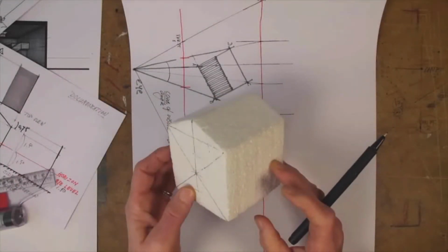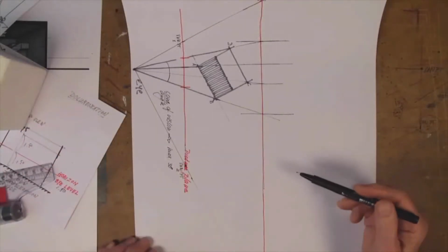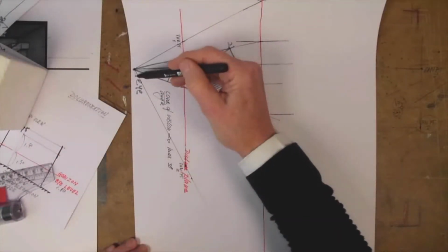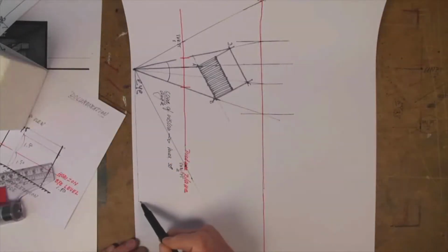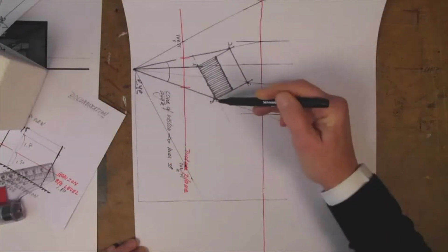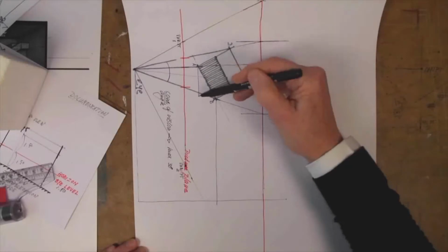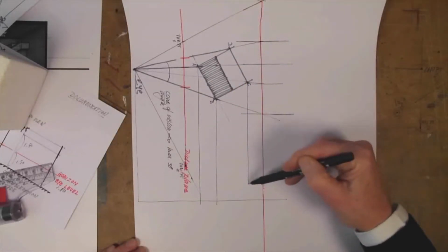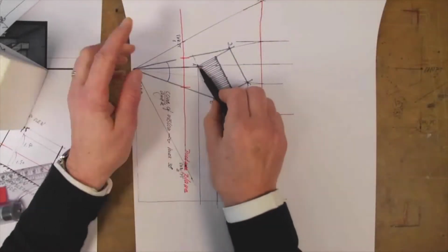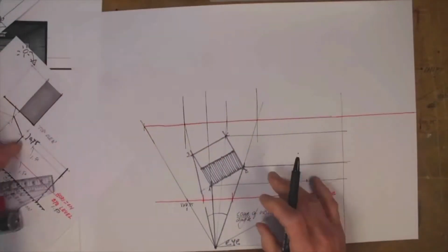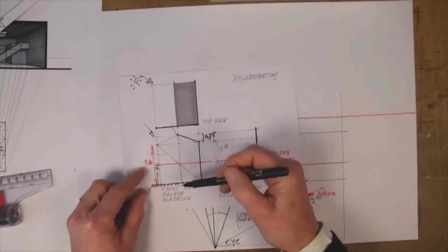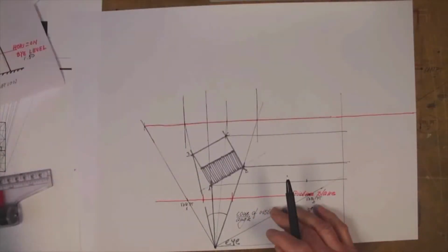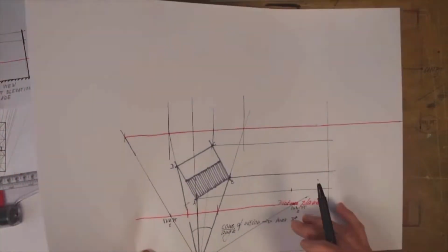I first walk away from my top view. Where I have empty space to make another drawing, I stop and make a ground line. Now you can draw the side view by drawing the verticals downwards from top view to the ground. What's the height of the house? The house is a cube plus a rooftop, being a quarter of the size of the cube. For the cube, the first rib has the same size in the elevation as the sides of the plan or top view.